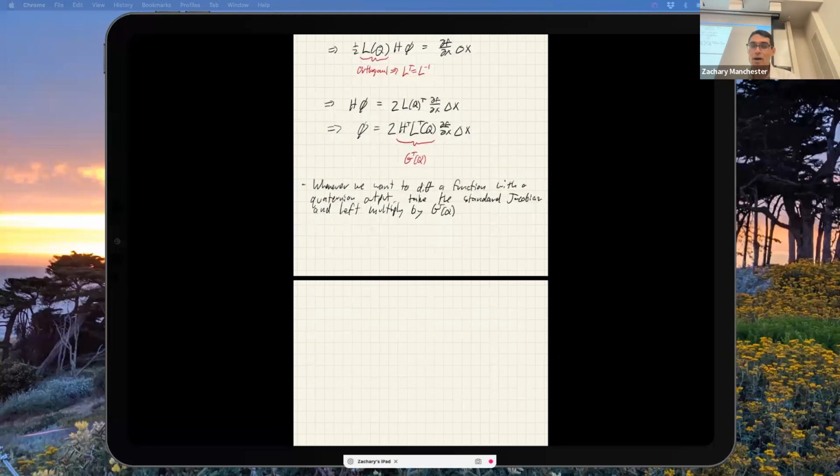Okay, and then the bottom line, I'll say this for next time. Essentially, we're just going to use this on the kinematics. This is going to let us map from quaternion things. When we do the kinematic Jacobian step to get velocities, it's going to give us omegas instead of quaternion derivatives, which are stupid and annoying and we don't want. And now when we have omegas, we can do our nice mass matrix stuff, and this generalizes. But we'll do this the next time because we're over time.